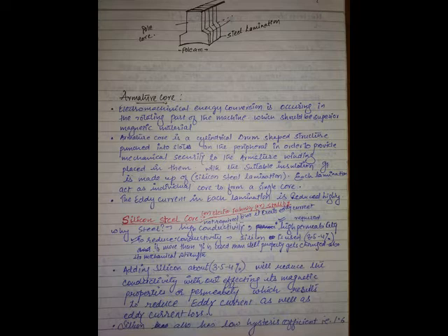Why you have to connect in series: let us say here three conductors are in series. I am representing the resistance as one conductor. In this conductor, by cutting flux, let there be 1 volt induced EMF. In this conductor, 1 volt induced EMF. In this conductor, 1 volt.